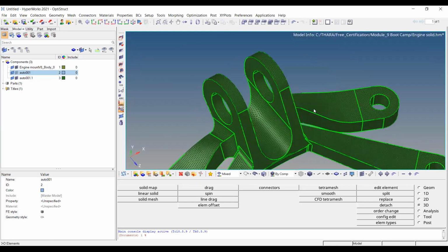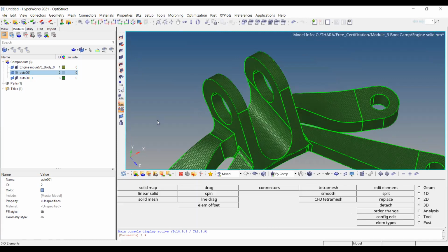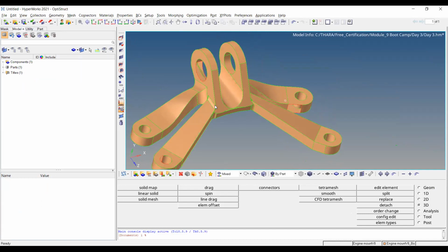So this is the reason that in most cases, we do not mesh using the volume Tetra. Using the volume Tetra, we are not going to create the elements. Then you can ask me, how do we create the Tetra elements? We'll create the Tetra elements manually. I have opened one more model in which we can create the tetra elements manually.